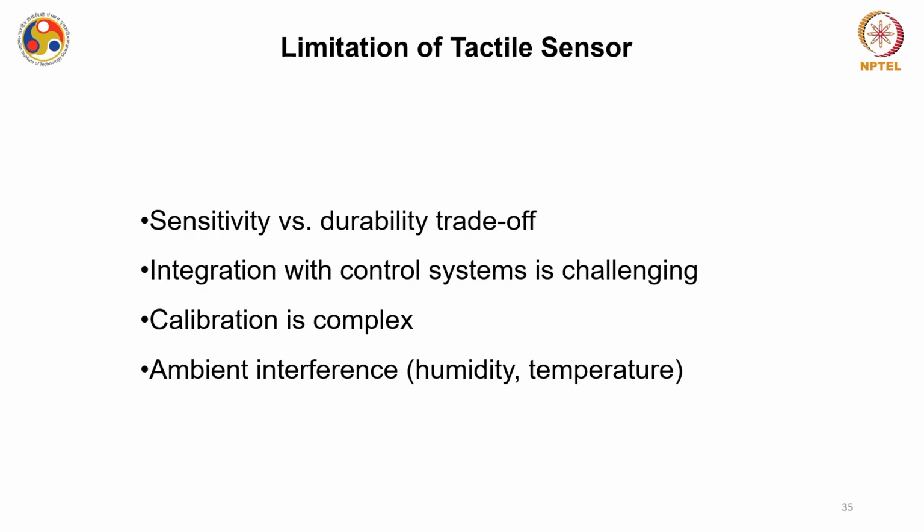However, there are certain devices, like optical devices, where this can be taken care of by the lens system and other things. Then integration of these tactile sensors with control systems is somehow challenging. These devices are also very difficult to calibrate, particularly because of the association of the threshold force, which makes calibration very complex.